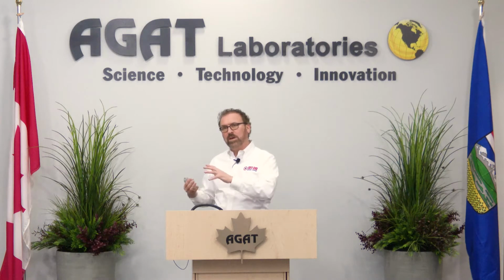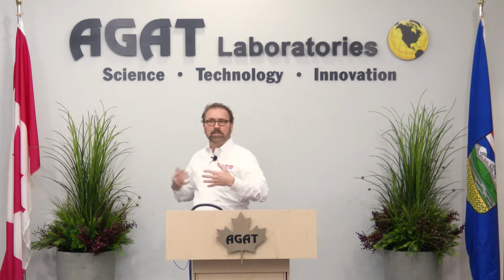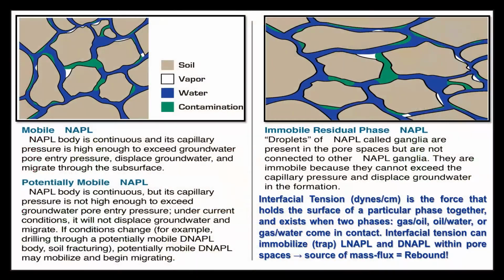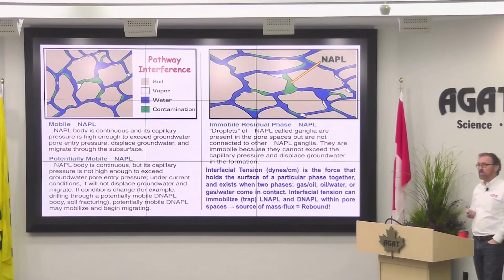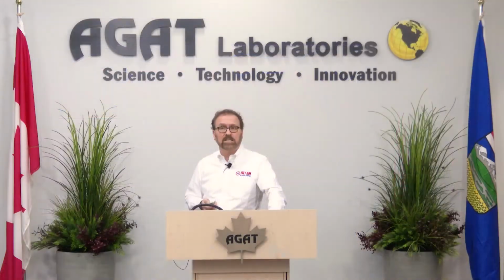But if the groundwater is moving, or you're trying to move the groundwater, it'll hit it just like a pier below a bridge in the river. It'll hit it and move around it because it can't get through it, and often follow a different pathway, leaving that contamination isolated and in some cases untreated. So be a little bit mindful of that. When it gets trapped there, we call that pathway interference, which can affect physical, chemical, and biological treatment. So that interfacial tension's a really important factor for vapors, which get sorbed, as do the contaminants, and then there's globules and free phase. They're all, in certain cases, going to be present on sites.